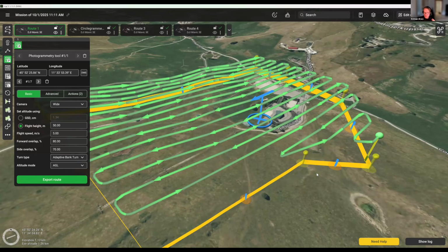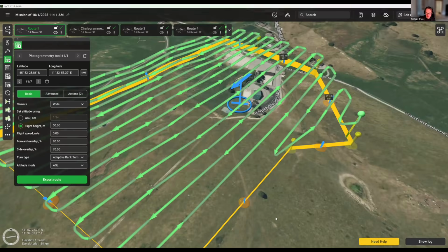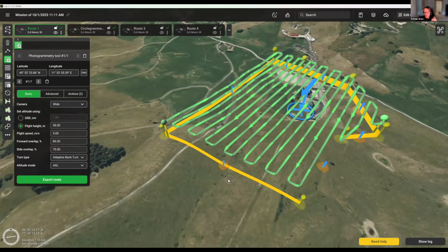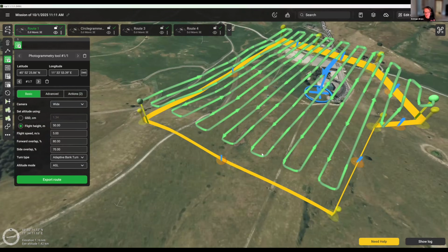What you cannot do in real time is alter the flight trajectory. So you can change the speed with the throttle stick, but you can't, for example, suddenly say, okay, I want the drone to fly the same mission, but 10 meters higher, and change this in real time. What you can do in those situations, where maybe you have flown some part of the mission and you want to fly a bit higher or change some parameters, but you don't want to re-upload everything.